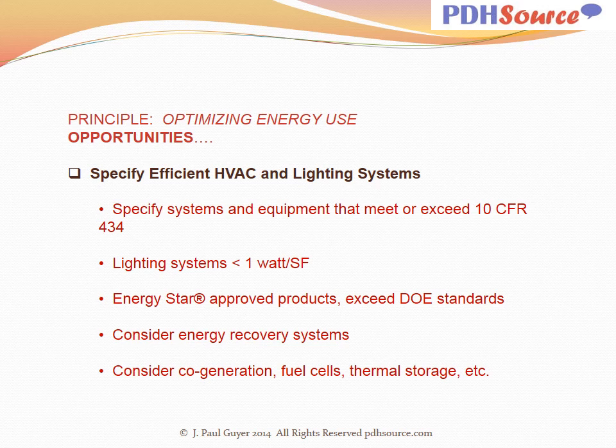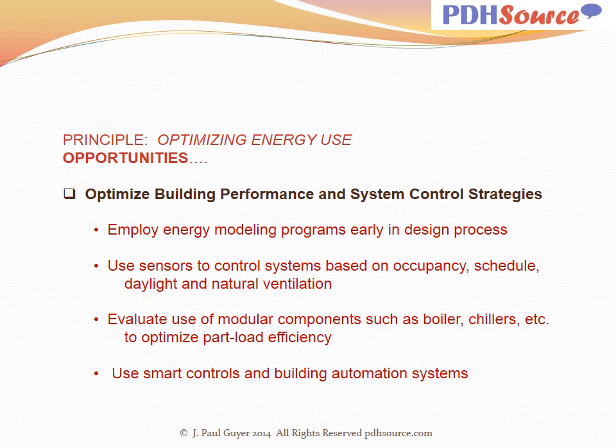So you may be able to use that high temperature water through energy recovery to do something else, like preheating industrial water or preheating domestic water systems, and so on. Maybe you might have an application for other kinds of exotic things, cogeneration, fuel cells, thermal storage, etc. Keep your eyes open for those.